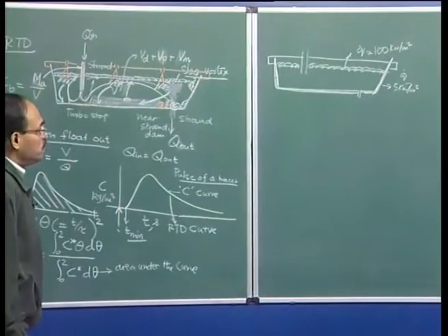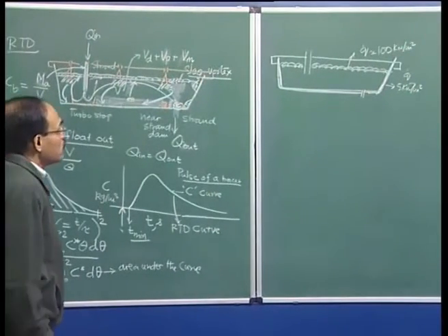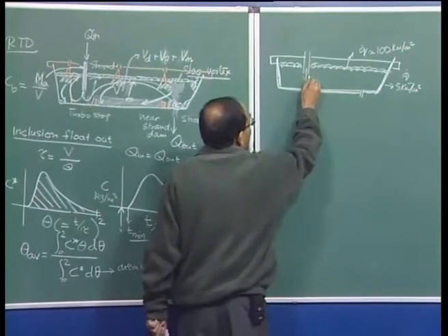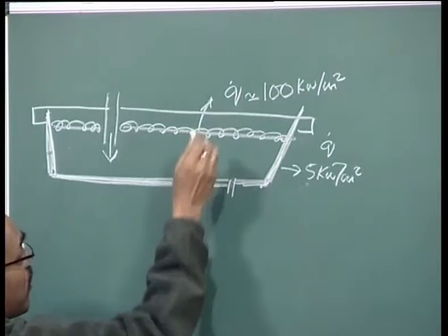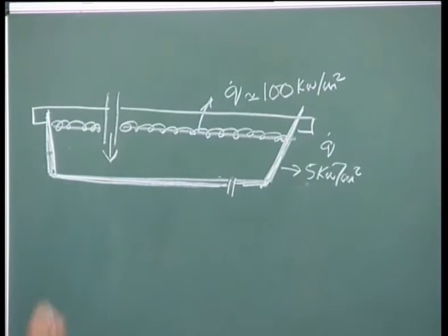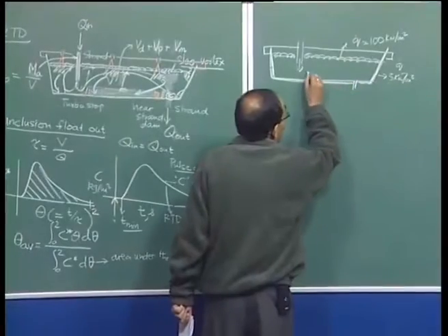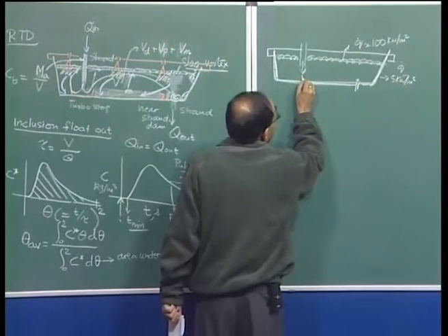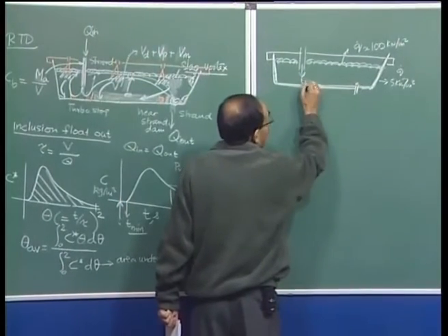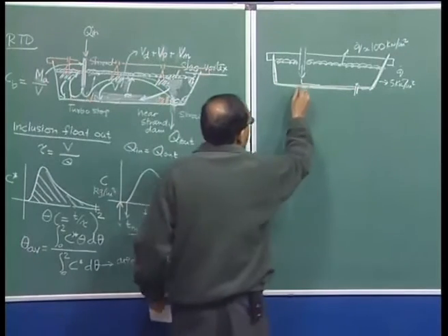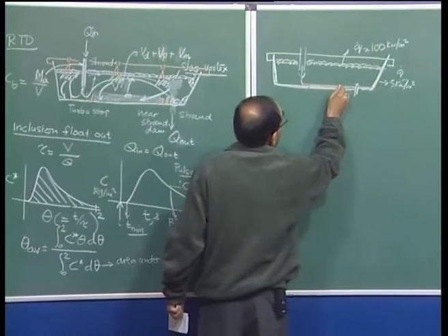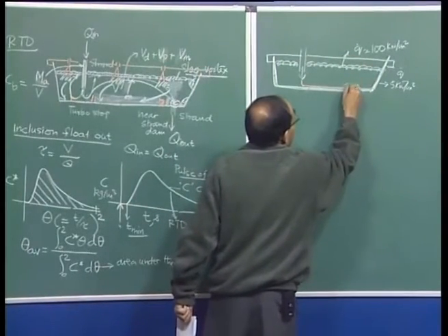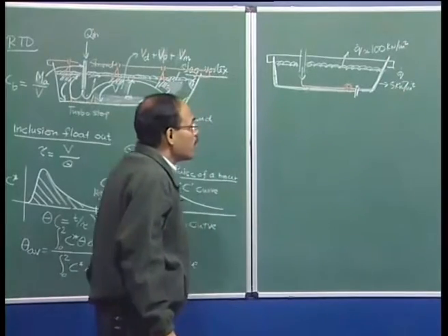Now, if you pour molten metal typically at a high temperature, it is because people think there is going to be a lot of heat loss in the tundish itself, and you do not want premature freezing in this part. The material comes in the ladle, the material flows, so the tundish is not filled up. The material enters the tundish and flows, and if there is too much heat loss, by the time the material goes here, it will lose so much heat that it can actually solidify here, which can create problems.